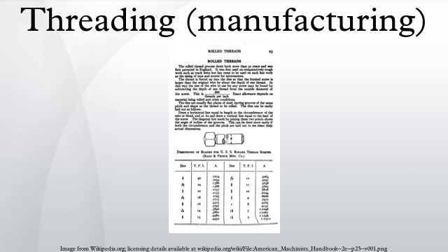Forming and rolling produce no swarf, and the blank size starts smaller than a blank required for cutting threads. There is typically a 15 to 20% material savings in the blank, by weight. A rolled thread can often be easily recognized because the thread has a larger diameter than the blank rod from which it has been made. However, necks and undercuts can be cut or rolled onto blanks with threads that are not rolled. Also, the end of the screw usually looks a bit different from the end of a cut thread screw.